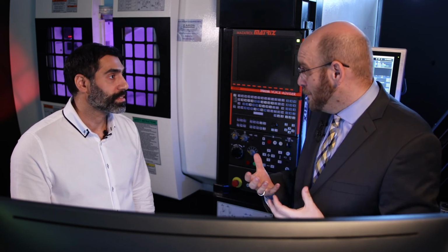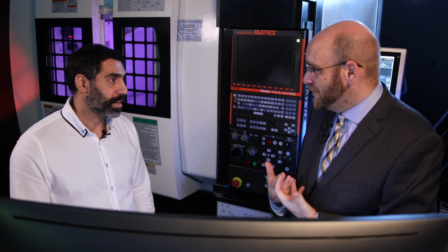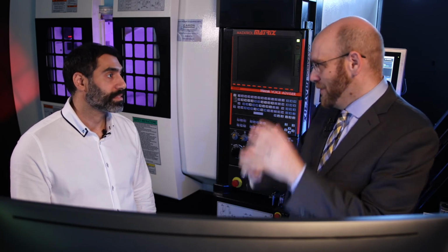I'll give you a real-world example of where this has been a great way for, usually the CAD system talks directly to Mastercam. I actually used this recently to bring in some PDF files, save them as DXF files, and bring them into a CAD system. So that way the CAD system could have the data from the PDF. And then from there, they had full parametrics, full solid modeling capabilities. We were able to make a solid model, and then we brought that right back into Mastercam. Oh, nice. So we used it as a translator.